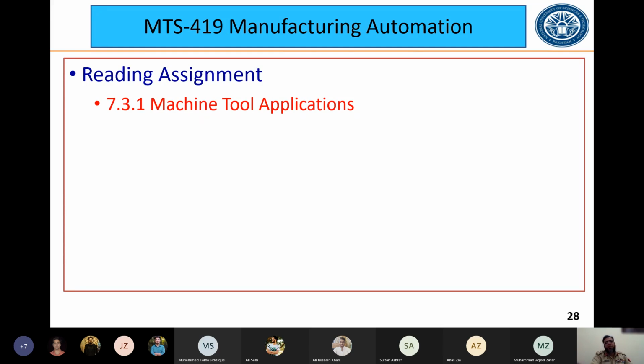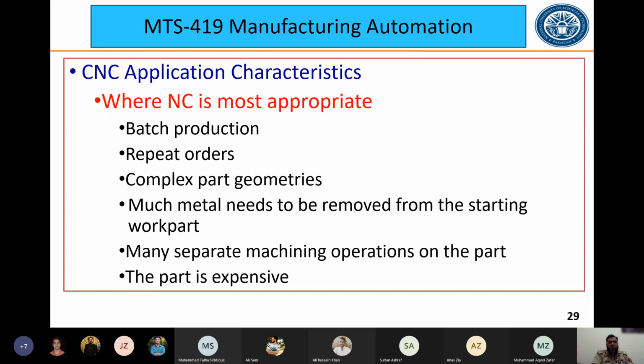In fact, this gives you the idea of selection of the speed of rotation of your tool according to the feed, according to the material. तो आप ये पढ़ेंगे, so you will come to know how the speed of the machine, the rotation of the cutter or the rotation of the work part is set, keeping in view different parameters. ठीक है, so this is your reading assignment.